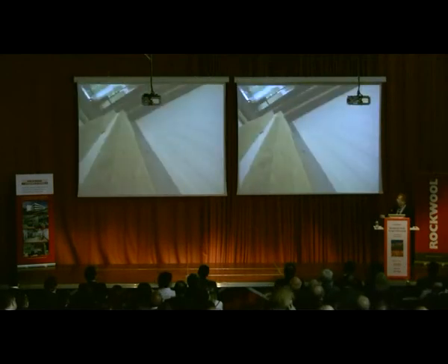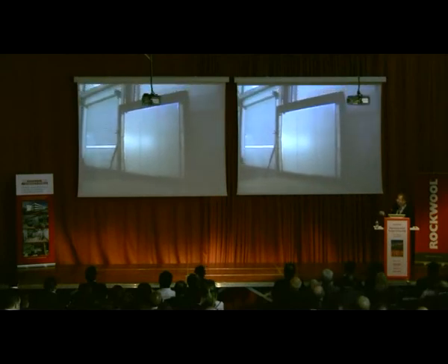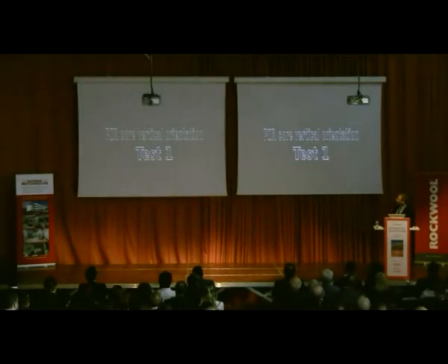So this is what the construction looks like before the test from the exposed side, and here from the unexposed side. So what we are going to measure here on this wall are temperature on different points. We are going to measure deformation of the panels.